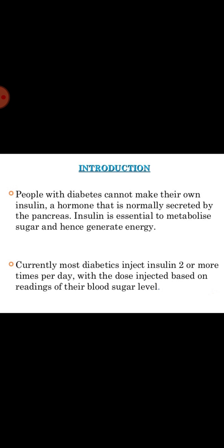Infusion pumps, rather than depending on gravity to generate flow, develop pressure by one of several electromechanical means. Mainly two methods are used. One is the syringe pump, in which a motor, through a gear reducing mechanism and a lead screw, applies force to the plunger of a syringe containing the drug. So the device is mainly convenient for applications that require the delivery of volumes limited by the syringe size.